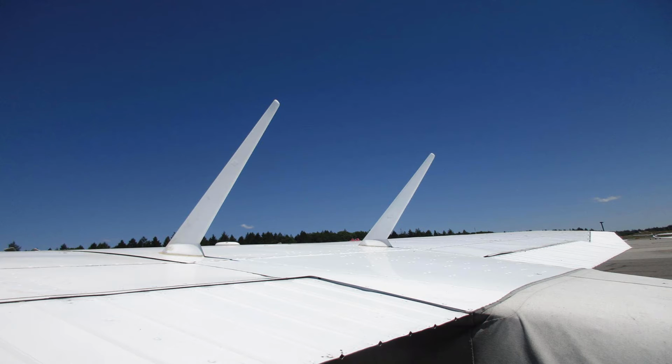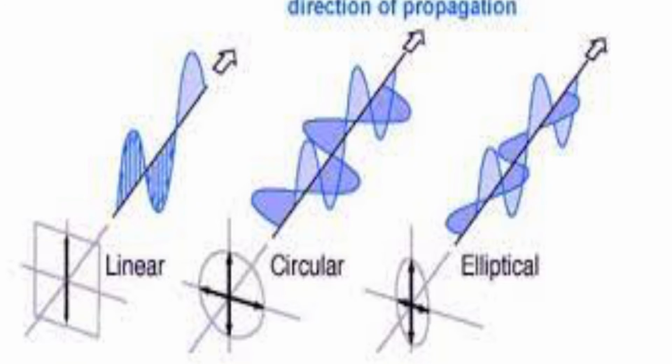Most radios, especially communication radios, use the same antenna for transmitting and receiving. VHF radio frequencies used by aircraft communication radios are 118 to 136.975 MHz. The corresponding half wavelengths for these frequencies are 3.96 and 3.44 feet. Antennas 1/4 the length of the transmitted frequency are often used. This is possible because when mounted on a metal fuselage, the ground plate is formed with the fuselage and acts as the missing 1/4 length of the half wavelength antenna.